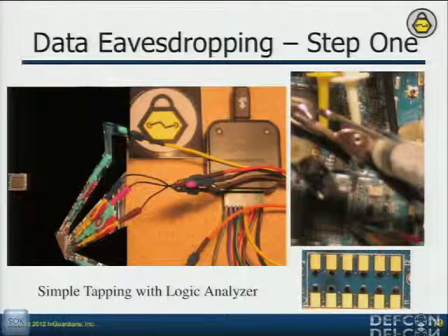Actually, the image that you see right here is the microcontroller driving the radio, which is this really small chip, because the radio doesn't have enough memory to keep that. So the microcontroller has to manage it. It has to send it the next hop, the next hop. Who understands frequency hopping? Okay, if you monitor these lines and you save them off to a file, now you have the hopping pattern for that particular radio. Now you can start using that for your analysis into other things like finding patterns, understanding how they're generating that hopping pattern. And if you can do that, now you're getting into the next phase that I really want to get into, and we're already working on that.